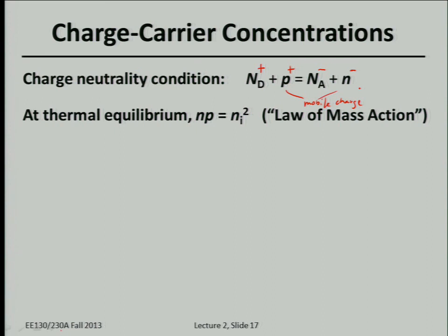So basically, if you increase disproportionately one, like p, the concentration of holes, you're going to decrease the concentration of electrons, simply because anytime an electron and a hole come together, they recombine, and you end up with nothing. I mean, no hole, no electron, no conduction electron.